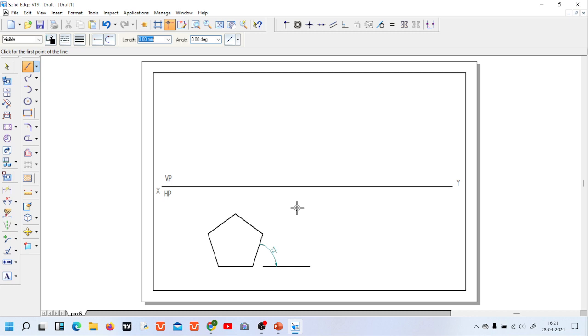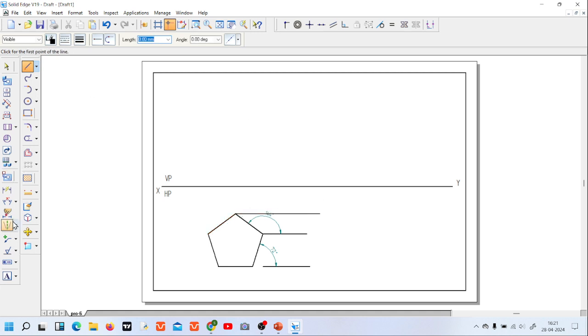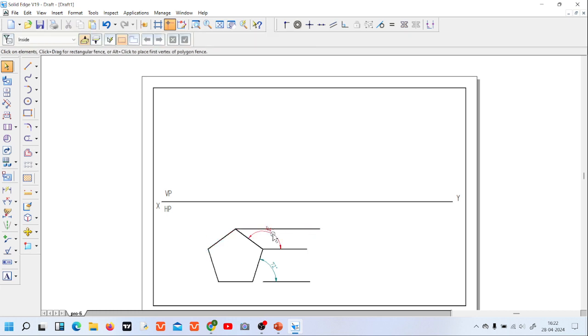you need to draw a horizontal line over here. So this is for your understanding purpose. It is 144. Similarly, if we get here, you are going to angle as in 216. It is 180 is a horizontal, 36. If we add it, it is 216. Okay. Now if you just observe, now the side is parallel to vertical plane.